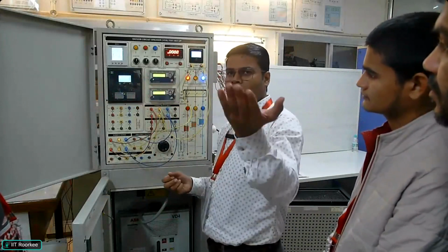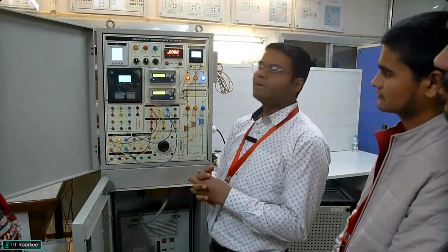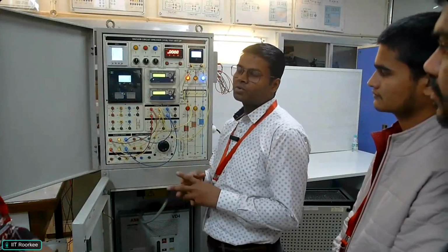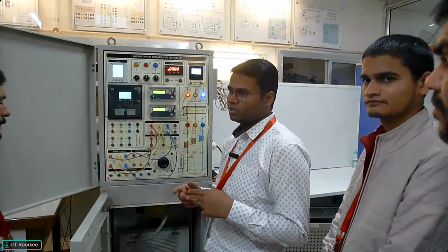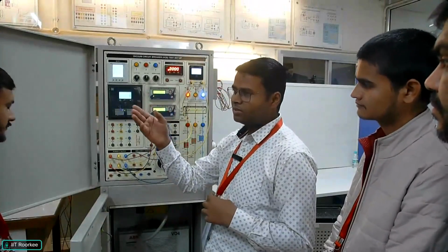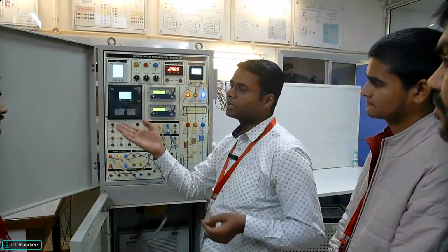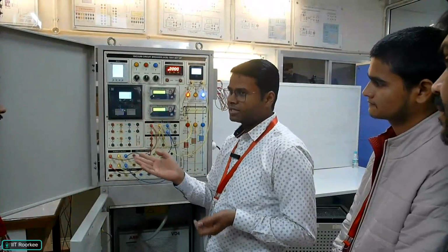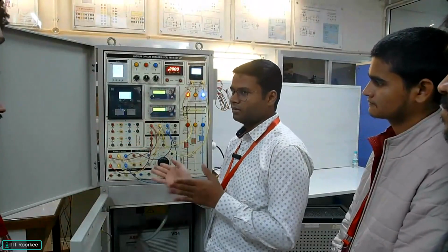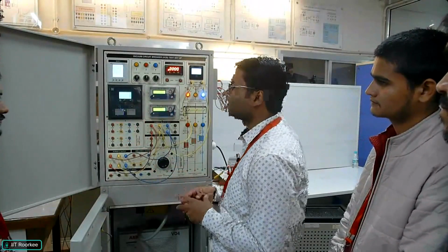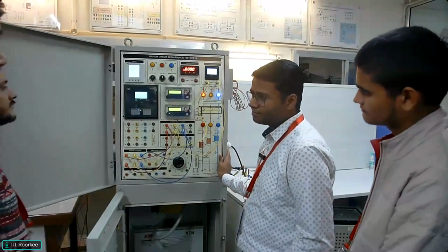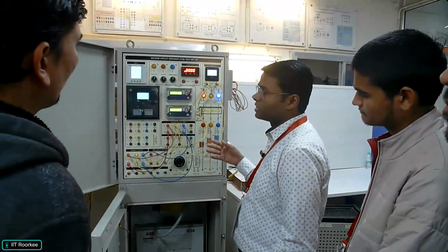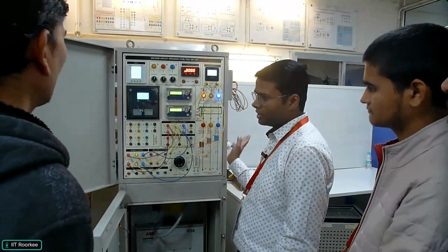So there are MCB, fuse, ELCB characteristics. What we were doing was showing them the low voltage circuit breakers like fuse, MCB, and contactor. In most of the operations for the circuit breaker we are using a contactor as a switch for separation. But here we wanted to also show them the main characteristics of the high voltage circuit breaker with the relay, meaning the relay coordination with that.